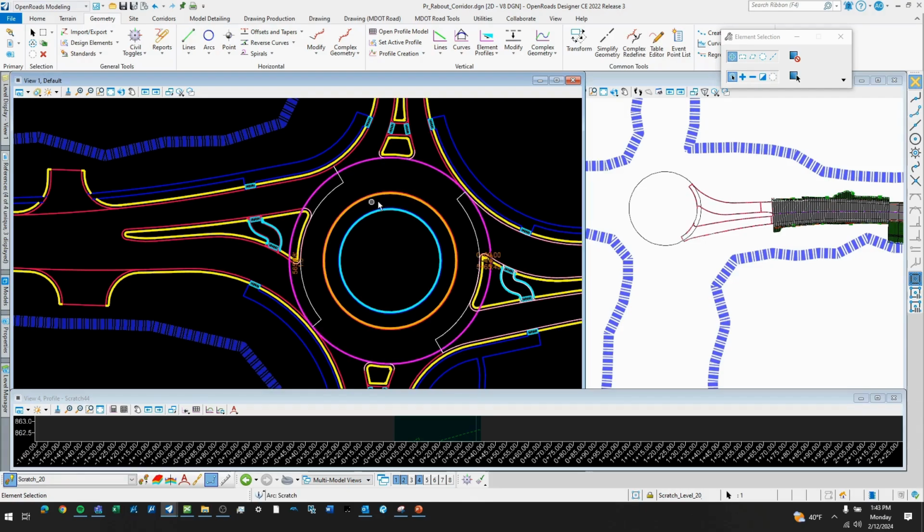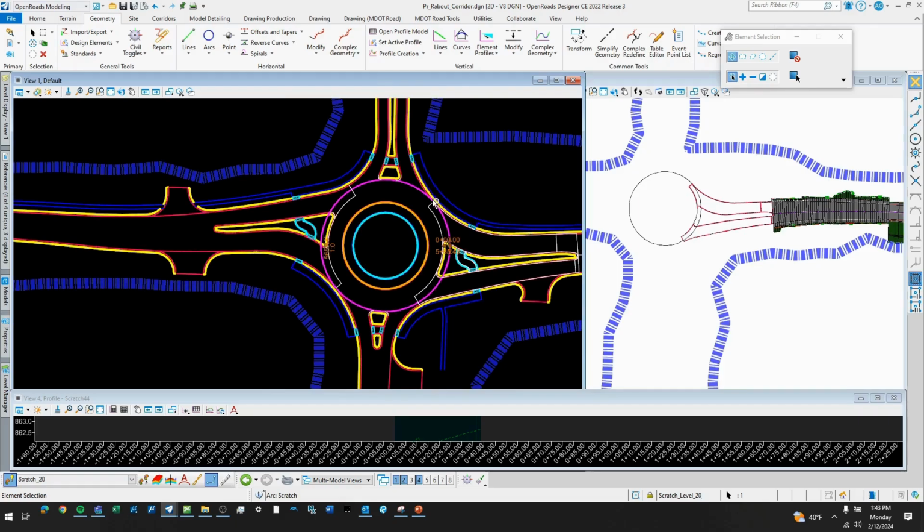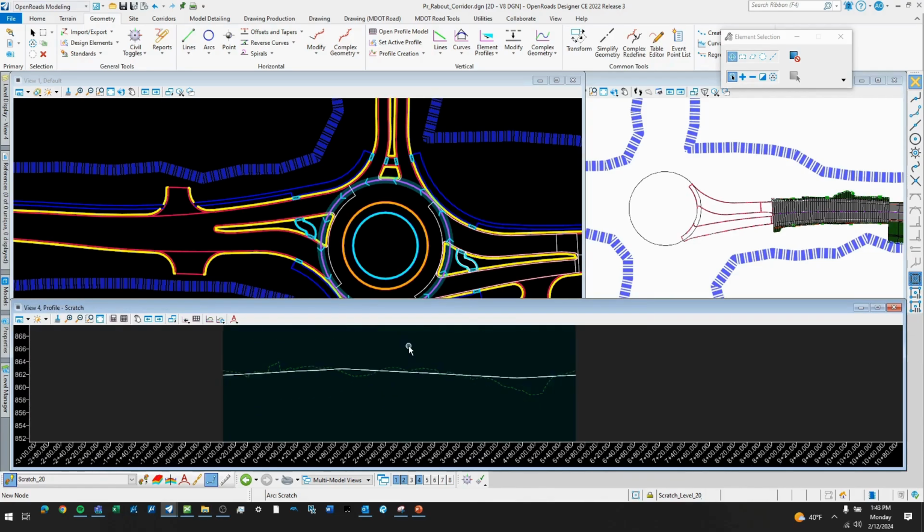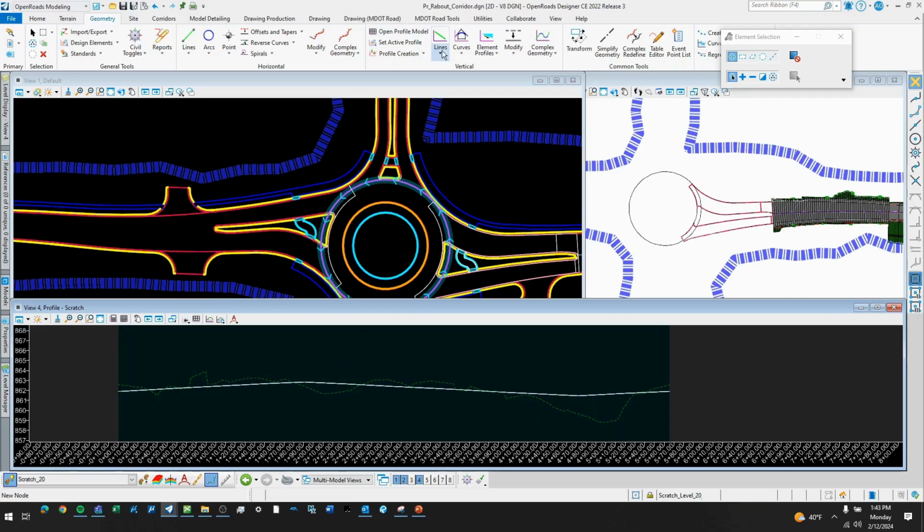In this example, again, we wanted this to be close to existing ground. Based on existing earthwork, I chose this to be that high point. It just made sense. There was already a pretty big ditch down here, so this being that low point, I think, worked out pretty well. And this is how I mapped that out.